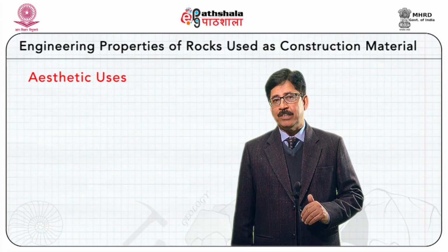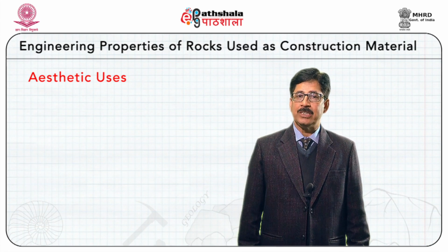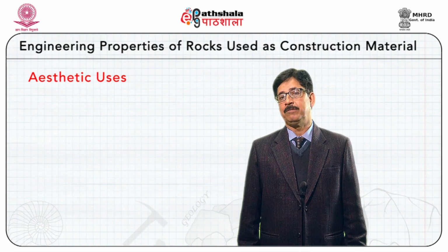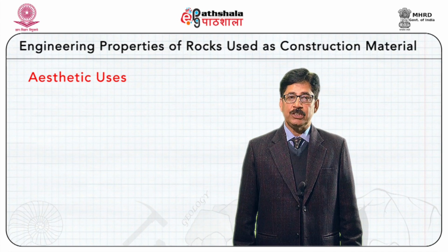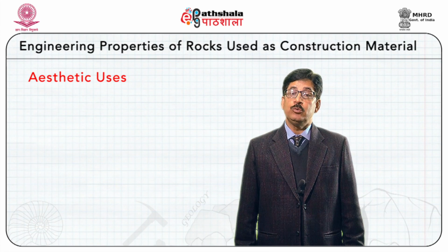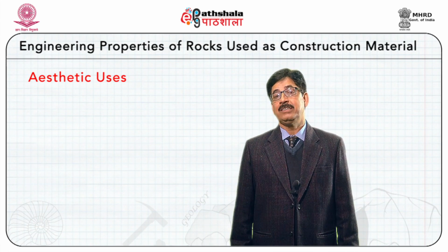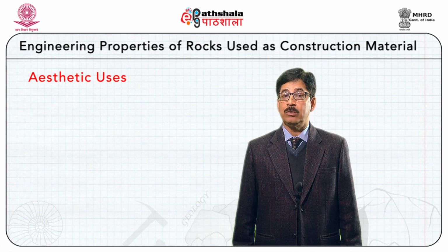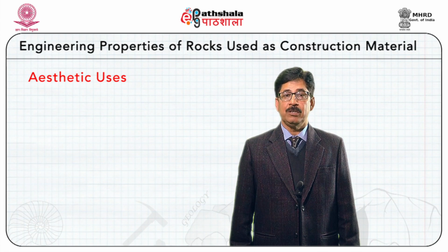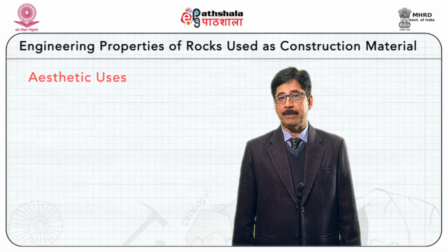Now, depending upon its different uses, we have some special properties of rocks. For example, when we use rocks for aesthetic purposes, then we need softness. Softness is a very important factor because we have to carve out different features into the rock. Now, what building stones we are going to use will all depend on which rock is available in nearby areas. So its availability is important, and its workability is important, that is, how easily you can work with these rocks in terms of breaking, cutting, chiseling and dressing. And then of course, durability is very important because when you are using building stones in some part of your building, you want it to last for a longer time.